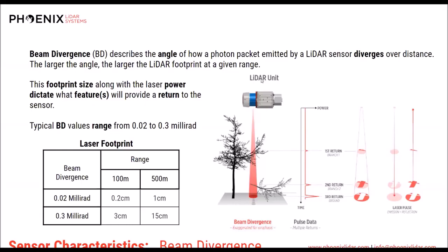Obviously, if you're collecting data at 4 points per square meter, you're going to miss a tremendous amount of power line information. So with that large caveat out there, I would not recommend anything less than 30 points per square meter for general power line mapping, but would very much recommend over 50 or 75. But once again, putting your eggs in the density basket is not necessarily the correct basket to approach collecting power line data. Think a bit about how your laser actually interacts with these for a given platform speed.